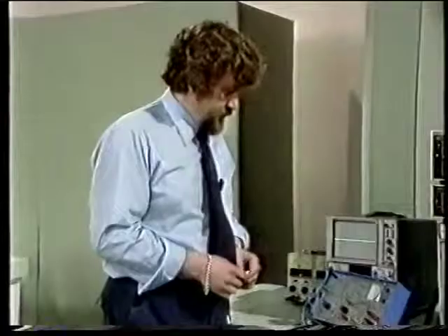But as you saw with the previous circuit, it can reduce distortion at voltage levels below saturation. Feedback is used a great deal for this purpose. A typical example is hi-fi amplifiers, in which, as you'll see in Unit 9, negative feedback is used to achieve the low distortion essential for high fidelity.